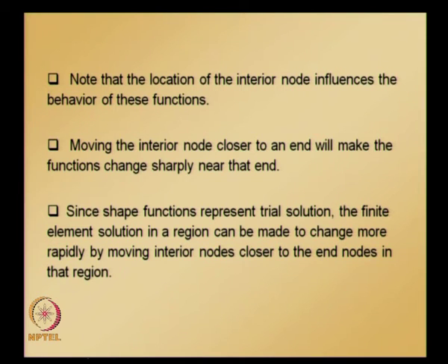So, now let us go to the next concept, isoparametric mapping. The basic idea of isoparametric mapping is that shape functions are used for transforming physical element geometry into a parent element with a simple geometry.